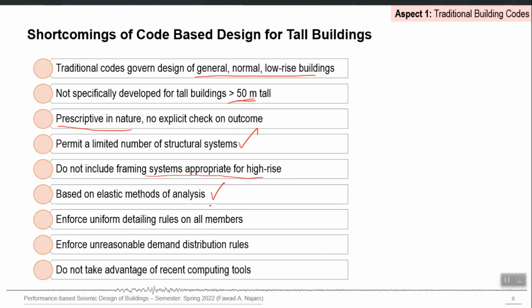The building codes always prescribe elastic methods of analysis, which means that the computer model you will be using for structural analysis and design according to a particular building code will always be an elastic model, right? A building code will not recommend nonlinear analysis because it is meant for the common engineer who can follow its general provisions. Nonlinear analysis is advanced analysis. Not everyone can go into its details, and also it is time consuming, and structural designers want a quick answer.